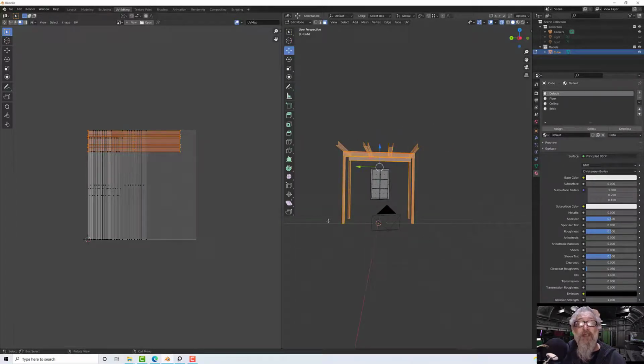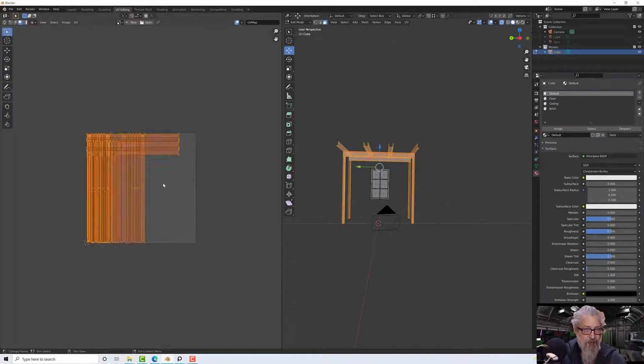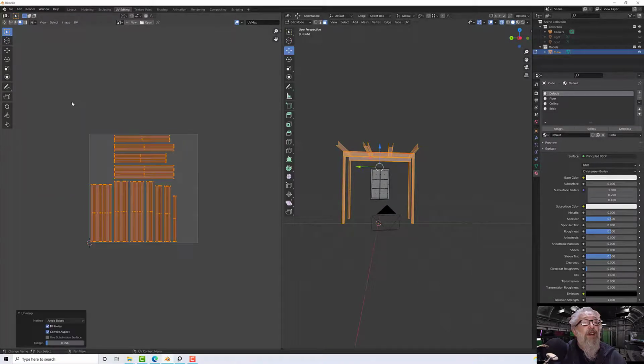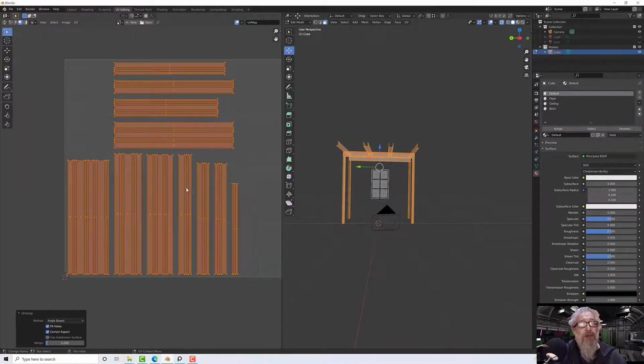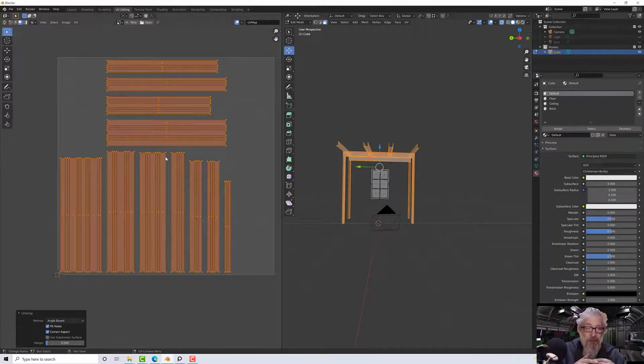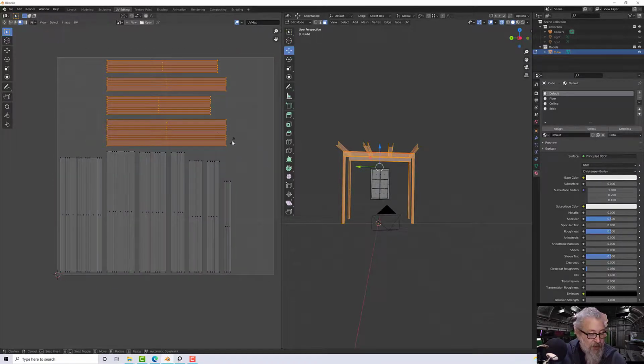and those ones, and we'll hit A over here twice in that case, and right click and unwrap. And I want all these pointing in the same direction, because when we texture it, the grain is all gonna go along the length of the beam or support. So let's just select these ones and rotate them round.